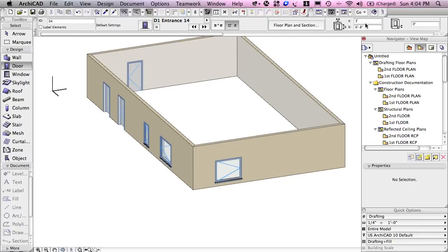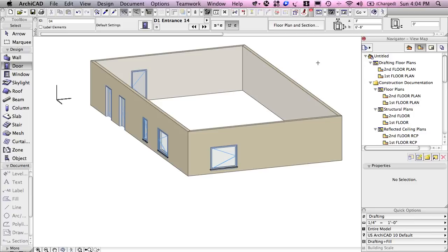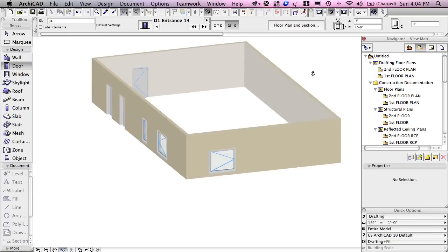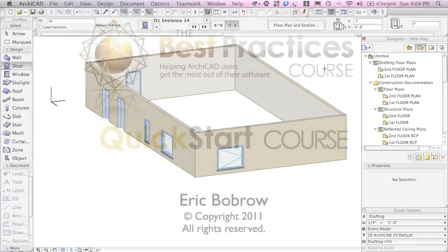There's another way that you can get access to the orbit mode, which is up near the 2D and 3D icons here, and here it has a slightly different icon. It shows sort of a building with a circle, but it's exactly the same thing. It does give you the extra little clue that to orbit you can type the letter O. So here I'm just orbiting, and I can turn it off again there, but I can also type O, and you see that it instantly brings that in, and when I type O again, it turns that off.